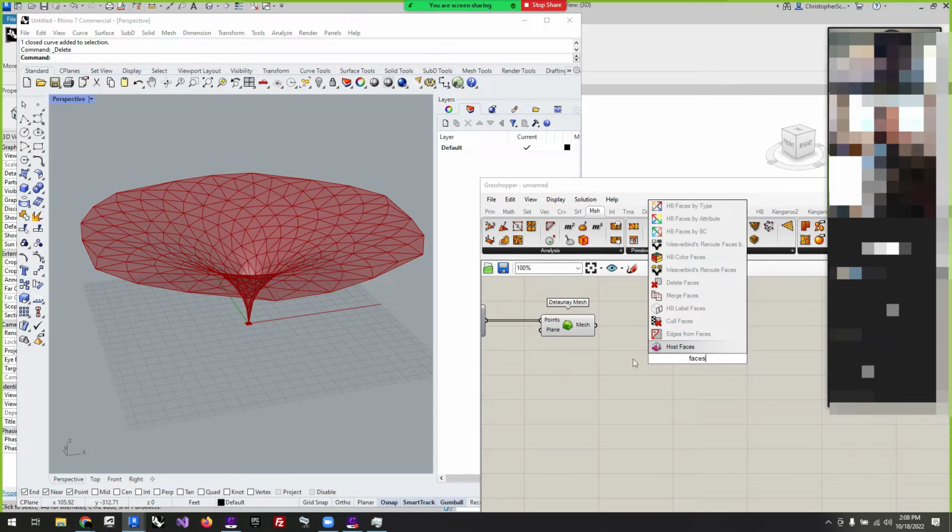It's going to give you your geometry. You're not going to be able to manipulate it in Revit the same way you would, and it's going to have a lot different relationship to any of your other elements in Revit. So it's a good bang for your buck operation to use direct shape as Rhino inside Revit, but it's not as robust as using native Revit elements. We're going to build our own family and use that to also bring things in.